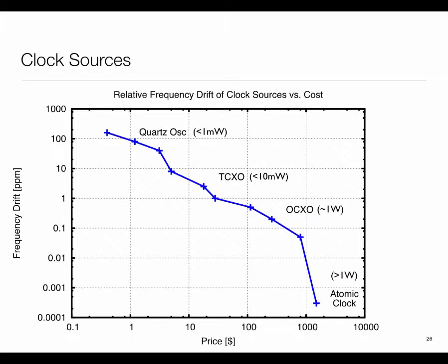So what that leads to is that we have a whole bunch of clock sources, and the primary thing as far as a clock source itself is concerned is really about the stability. That's really what you care about. Accuracy, as we learned, we could compensate for by calibration. Stability is a tricky thing, and that's what you pay for. So you have quartz crystals, you have TCXO, you have something called OCXO, oven controlled crystal oscillators. Literally, these are tiny ovens which maintain a constant temperature so that the oscillator maintains good stability.